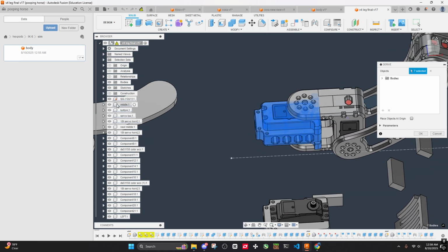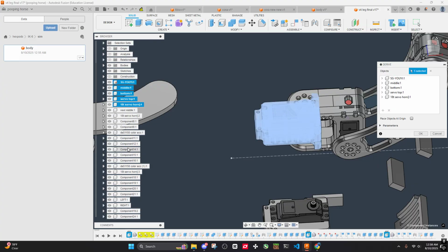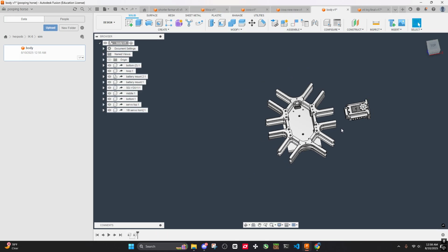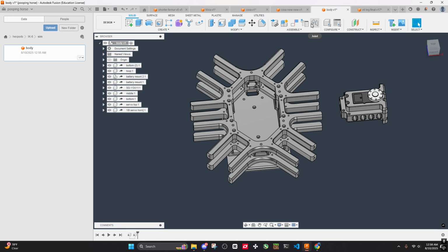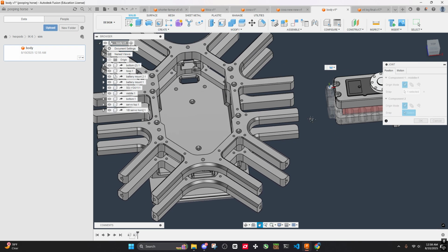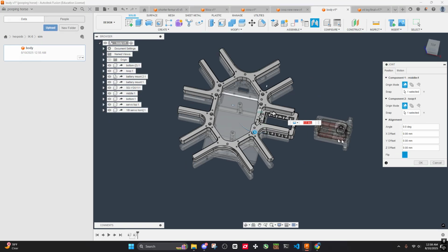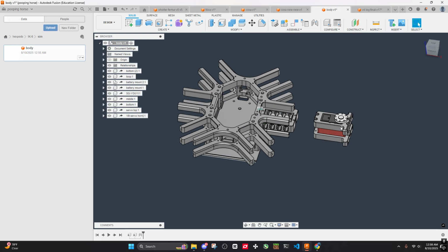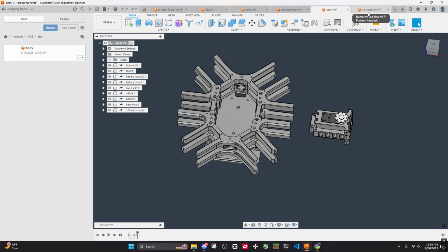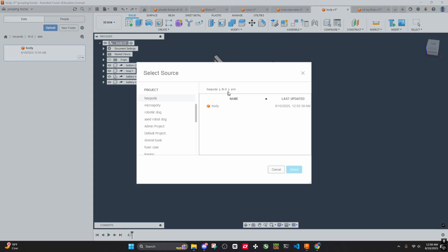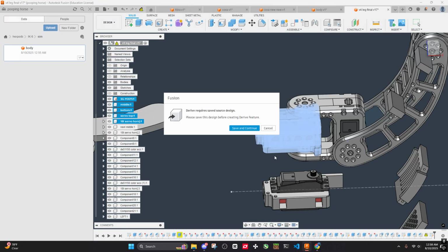And then I have to center it. About 4 each. Yeah, it looks like it's 4 each. And then on this side, it's at the origin-ish. Set origin, origin to, no, I need 3D cursor.